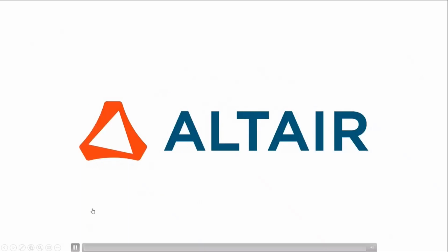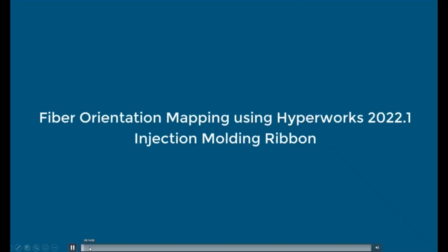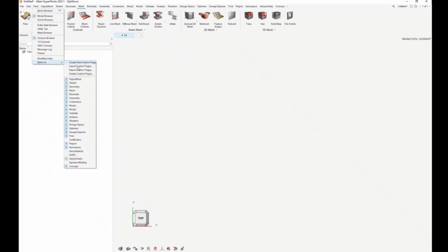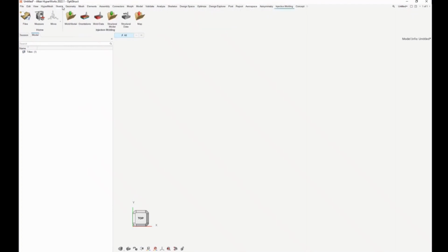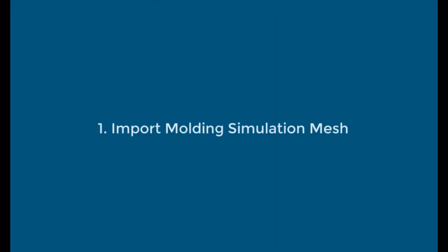And for this one, I have a bit of a longer video because there are a few more steps, and it's actually also a bit of a bigger model, so some steps take a few seconds. First thing, you need to enable the injection molding ribbon, but that's very straightforward. You go to View, Ribbons, Injection Molding, and there you go. You have your ribbon available.